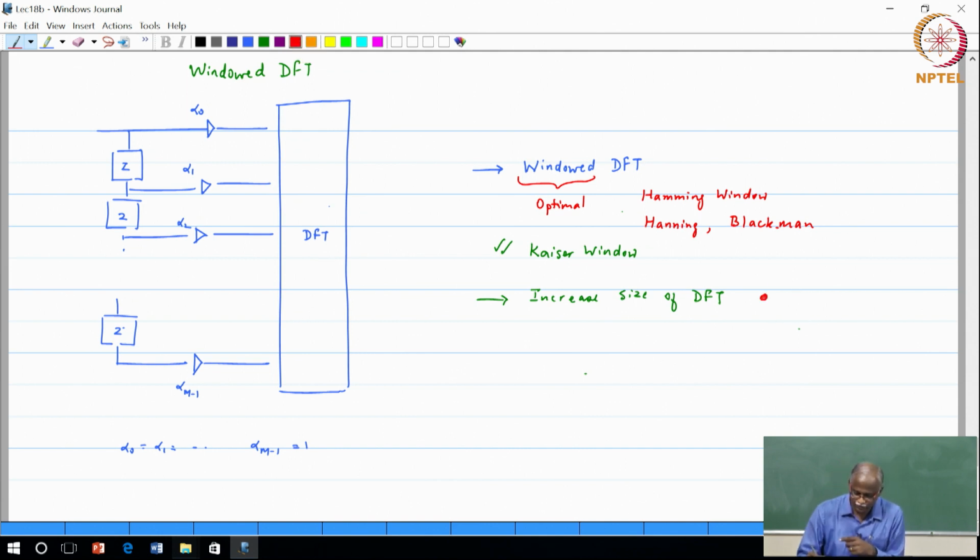Of course, windowing you can do, this one you may not be able to do, in which case let us say that the maximum DFT size that you have is M. I cannot go beyond it, but then I ask you, I want better resolution. I want a spectral analysis that is well resolved both in terms of frequency and spectral leakage. And then we go back and look at this structure. From a DFT point of view, you will say there is nothing I can do. I applied the best possible window, but you are constraining the size of my data set, so therefore I actually am limited.